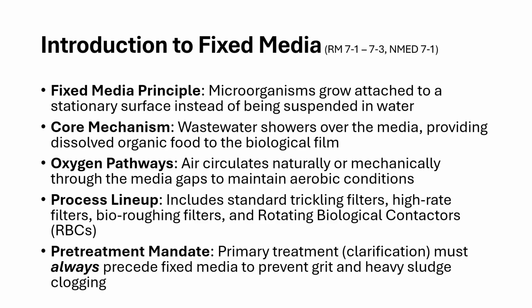We have a second type of device called a rotating biological contactor. And in those rotating biological contactors, we have these large drums with surfaces, kind of labyrinth or maze-like surfaces, whereby our biological film is attached to those surfaces. And we rotate these drums so that the film gets dipped into the wastewater with the organic load very slowly. And we just have these rotating drums or barrels, if you will. And that's how we facilitate the contact between the microbes and the organic waste load.